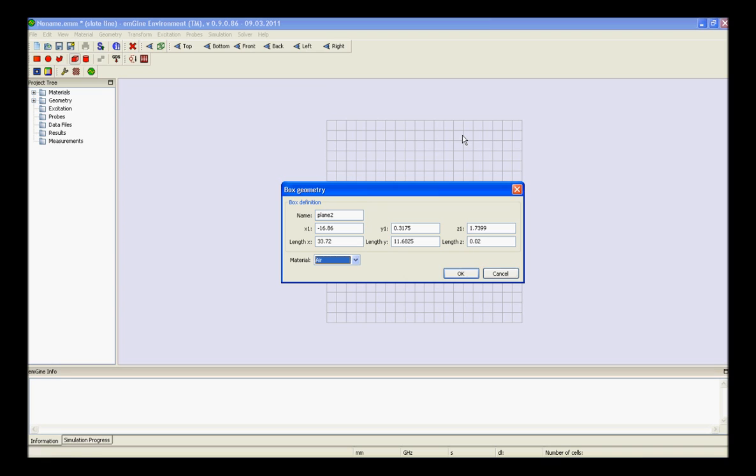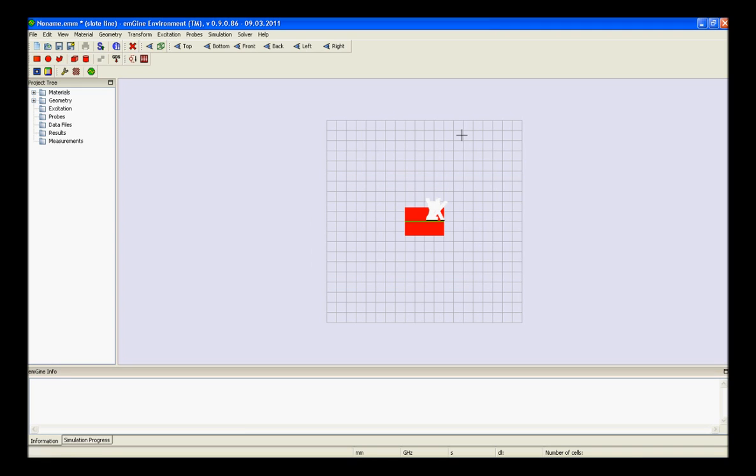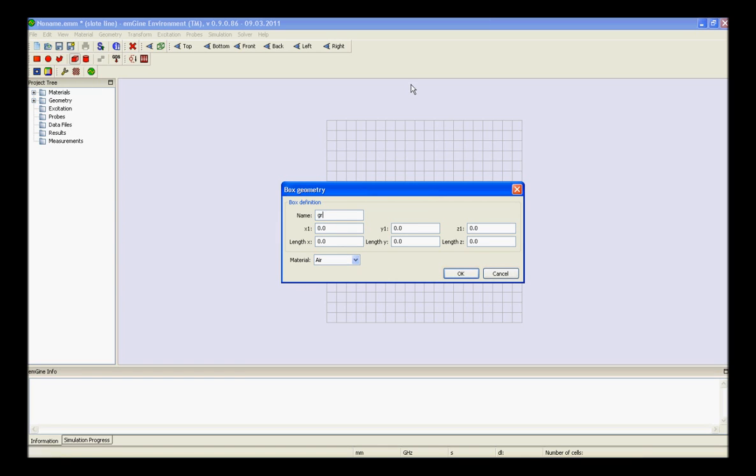Once we have done this, the next step is to model the ground plane below the substrate. Therefore, you should again do the same process. For the dimensions of ground plane below substrate, you should design the ground plane of PEC patch. The material setting of the brick must be changed to the desired ground plane. Also, we need to provide the values for x1, y1, z1, and then provide the values for x-axis, y-axis, z-axis, and also change the value of the material.